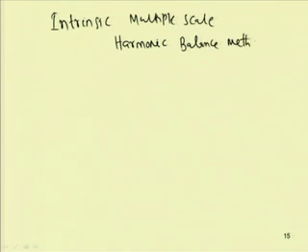So, we started with the ordinary harmonic balance method, in which we used this Fourier series in the governing equation, and by separating the coefficients of the cosine and sine terms, we get a set of algebraic equations which we solve to find the solution of the nonlinear equation. But with an increase in the order of the equations, or with an increase in the number of harmonic terms in the harmonic balance method, this method becomes very cumbersome.